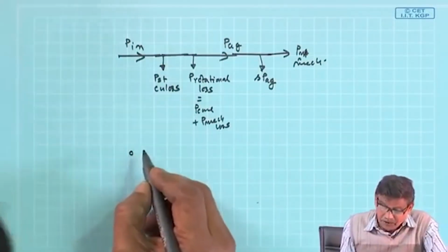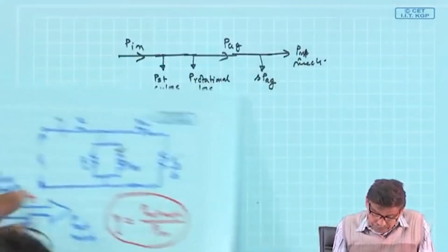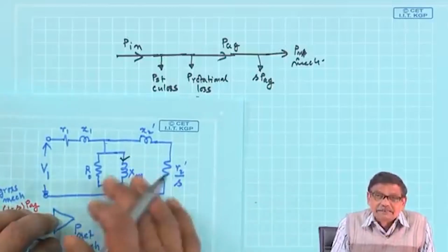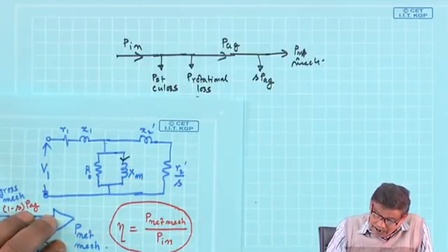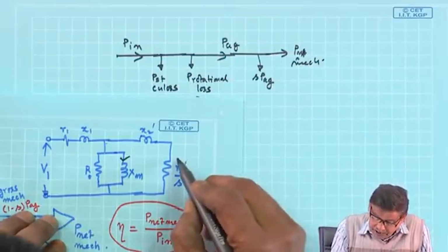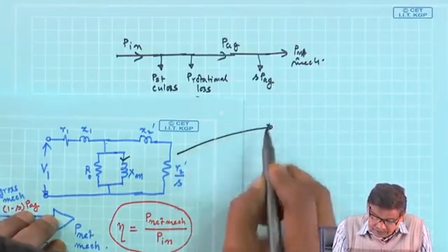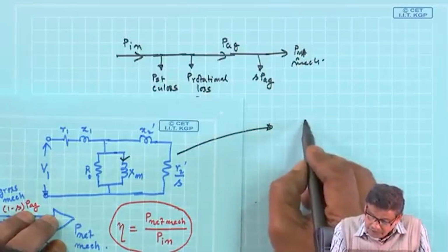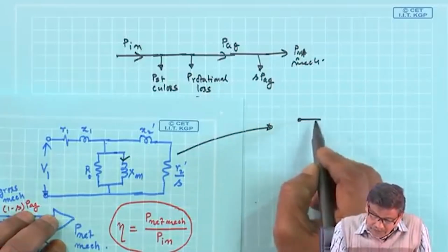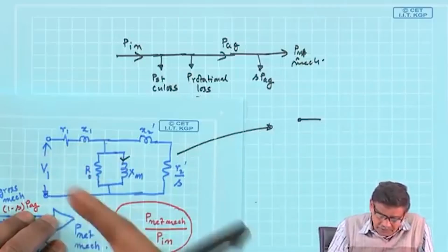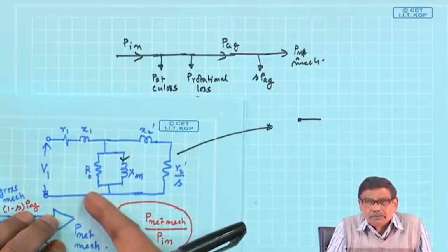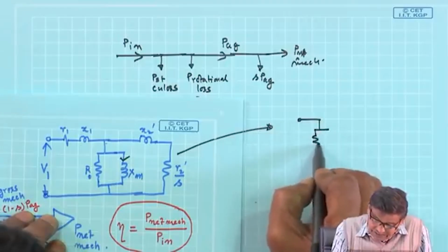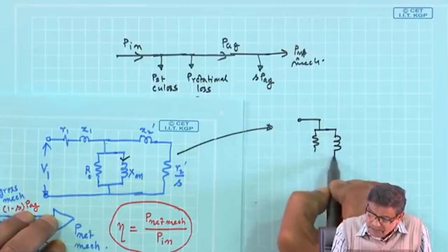So, this was the original equivalent circuit, is it not? Now, for this circle diagram, what further assumption will I make in this equivalent circuit? I will pretend like a transformer, with the plea that R1 X1 is smaller compared to R0 X0, I will bring this here.